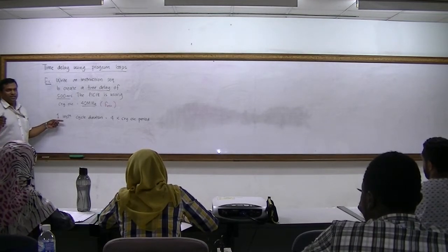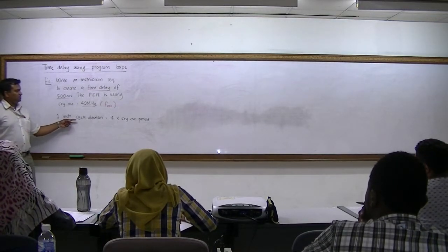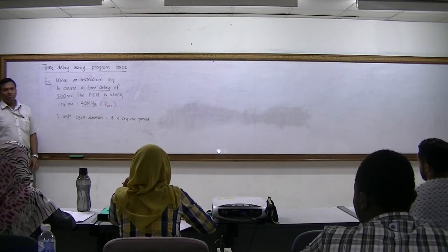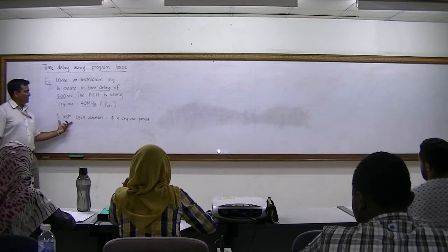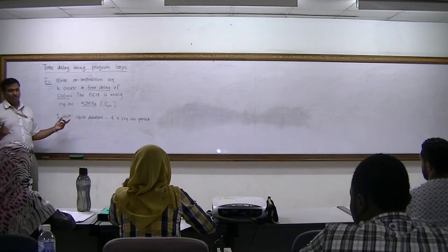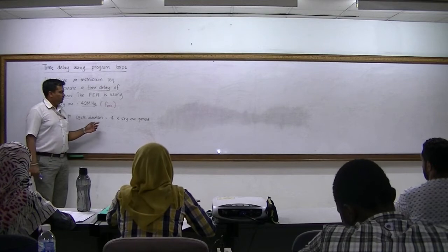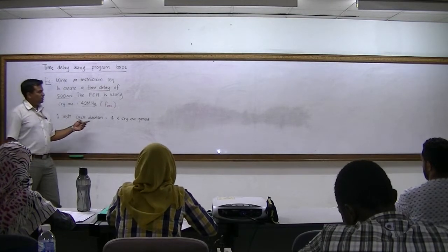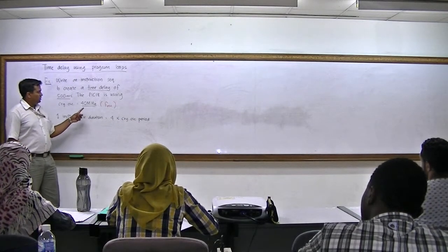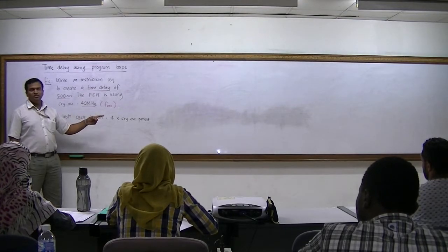In our instruction set, the column mentioned about cycles, right? That is this. This is one instruction cycle. So when we say instruction cycle, this is one instruction. Now what we want to find out is the duration of this one instruction cycle. How long does it take? The duration is equal to 4 times the crystal oscillation period. Now, is this period or frequency?